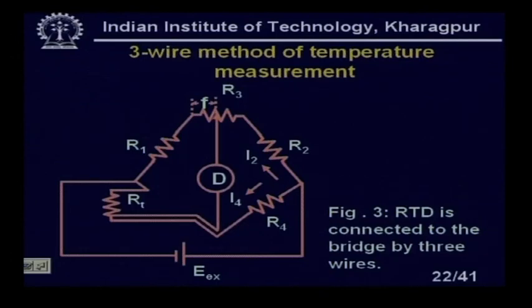So, this contact resistance is no more in the bridge circuit. No extra calculation is needed; whatever bridge balance equation we write will be absolutely correct, and the contact resistance will be in the detector circuit. It will make the detector more or less sensitive, but it does not matter, it is nowhere coming into the picture. I am denoting some currents because we have to calculate something.